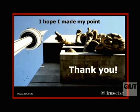If we look at all the simulation work that we do for predicting hurricane impact on the east coast of the United States, if we look at importing various climate change RCPs, representative concentration pathways, if you like, climate change scenarios, we take the worst case, it's about a 10% increase in wind speed for New York and the northeast of the United States by 2100.